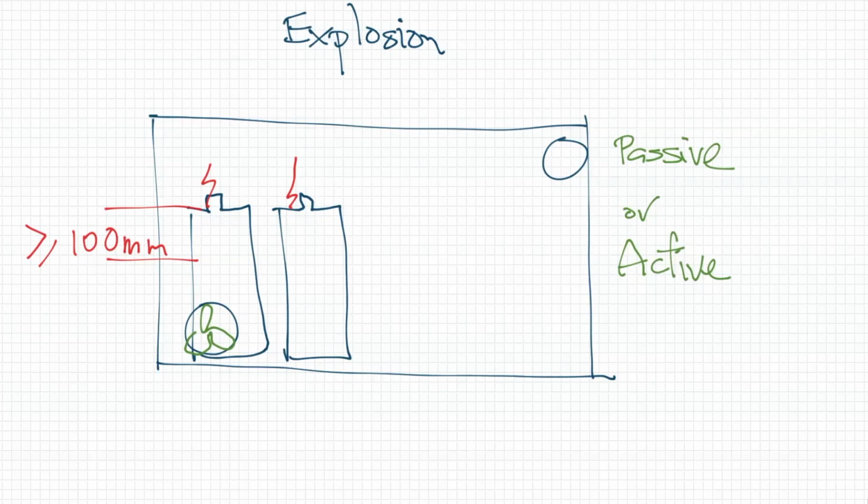So basically anything but a burglar alarm battery requires 2-hour structural, 2-hour integrity and 2-hour ingress of fire protection, which is really, really tough. That would make it virtually impossible to install a battery system in most buildings bigger than a burglar alarm battery. You would find very few data centers and UPSs would even comply with it. So it's kind of been a strange sleeper in the National Construction Code. I believe they've not taken it out until this standard's been published. And so I imagine with the next iteration of the National Construction Code, they'll just point simply to this standard and stop having this slightly outdated clause about little tiny batteries.